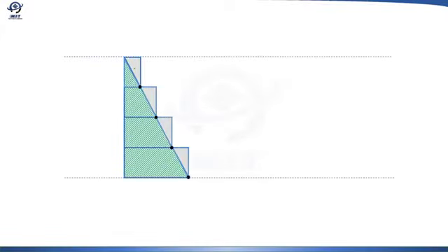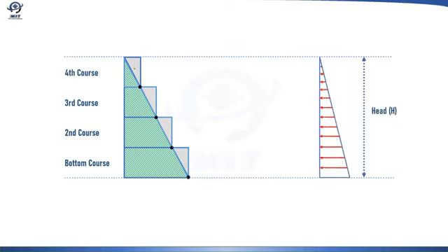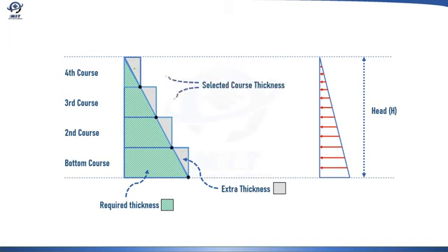For a storage tank, the hoop stress is mainly developed due to static head of the stored liquid, so the profile of the stress will be like shown here. And often for medium and larger diameter tanks, we can select lower thicknesses for plates on top shell courses, as the stress will be lower due to lower hydrostatic head on the top shell courses. API 650 tank has two methods for calculating tank shell thickness, namely 1-foot method and variable point design method. And a comparison between the two will be presented in a later slide.